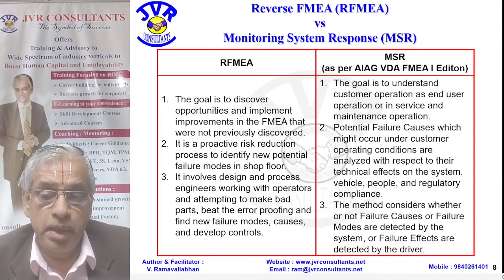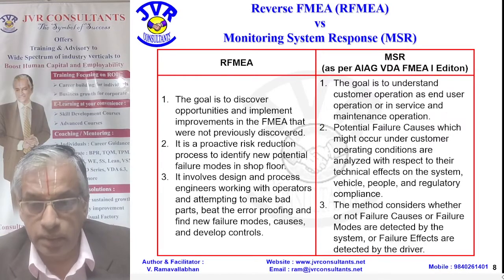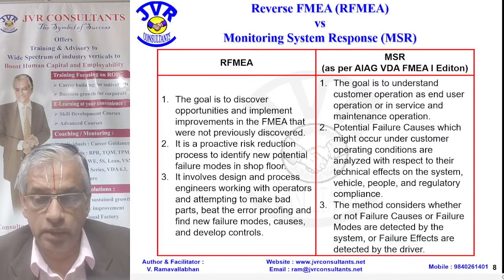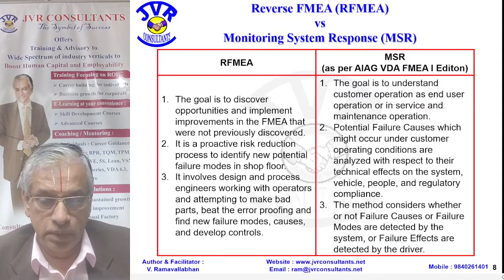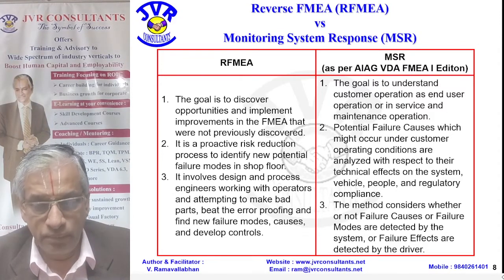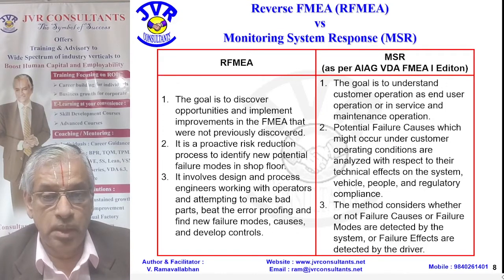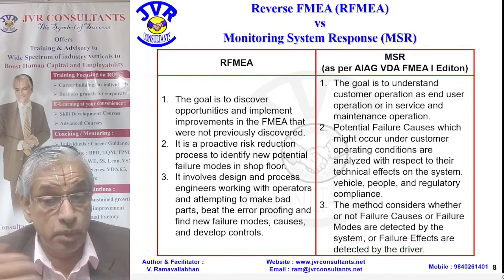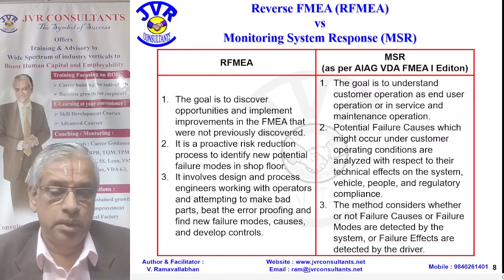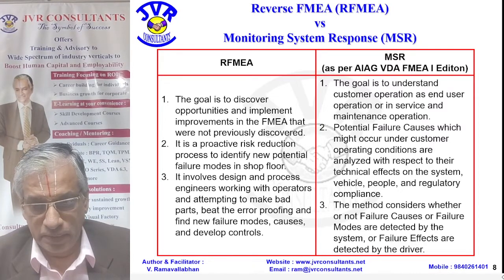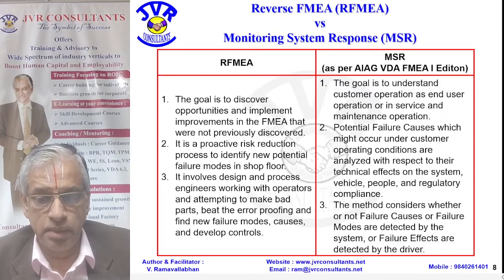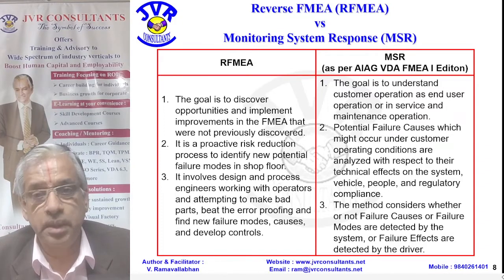So it has to be analyzed with respect to their technical effects on the system, vehicle, people, and regulatory compliance. If some defect happens, what is the impact, the technical effect on the system or the vehicle itself, or the people who are operating it, or any regulatory compliance. The method considers whether or not failure causes or failure modes are detected by the system, or failure effects are detected by the driver.